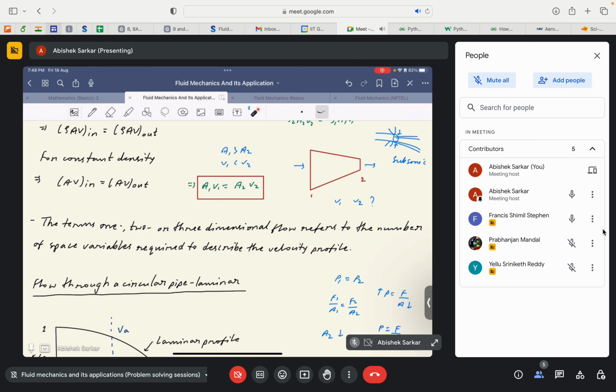See, yes, you are correct, but force does not necessarily arise because of viscous effects. Force can be because of the pressure gradient also, as well as the body forces, right? For example, gravity and electromagnetic forces can be regarded as forces that drive the flow. So we cannot only say that viscous effects act as the force in the case of fluid dynamics. So I guess that's the case.